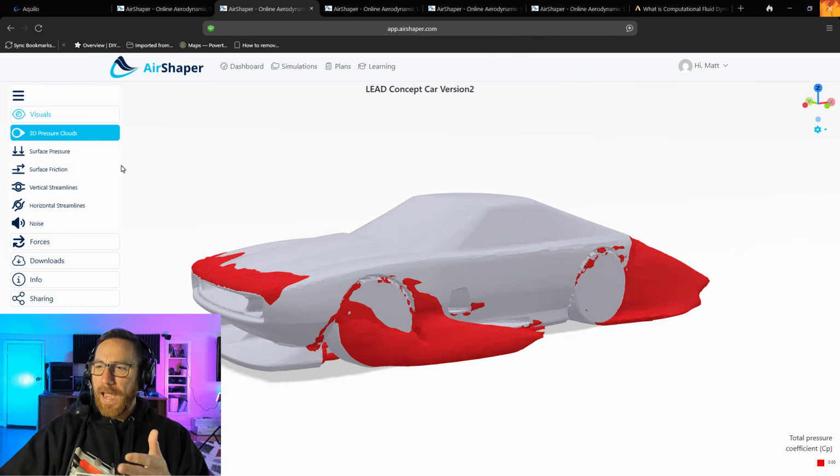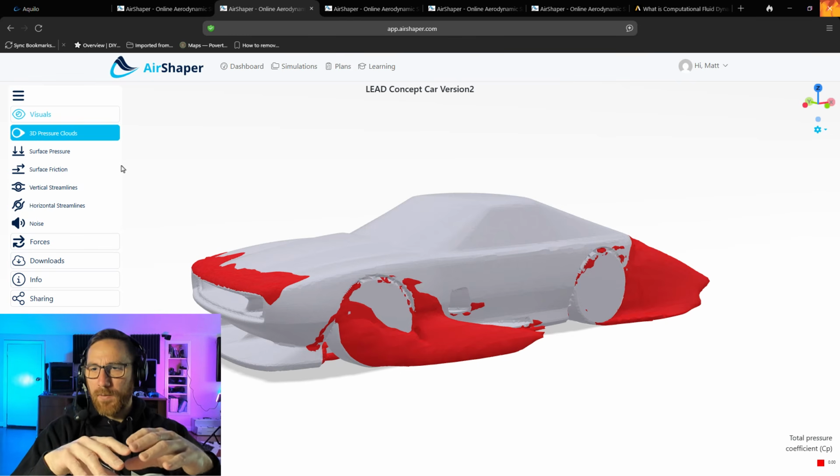And they were fairly accurate. When I say fairly accurate, there is going to be a level of difference between the forces that you'll see in the same exact model solved in low and medium res. That's because when you get higher resolution, you get more cells around the car. The mesh model is a higher density, and so it's more accurate to the original concept.